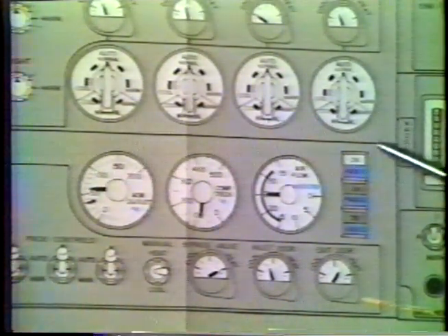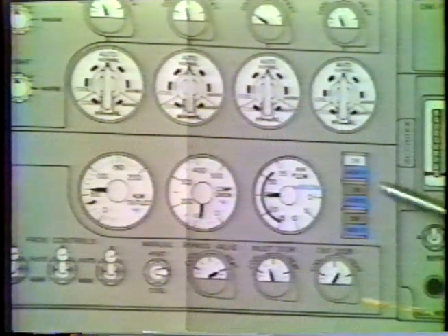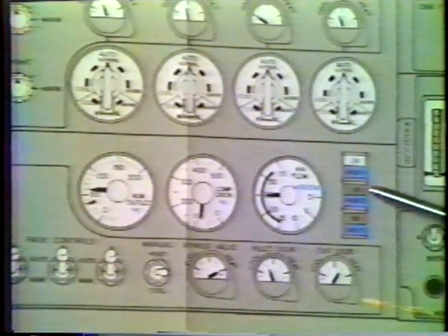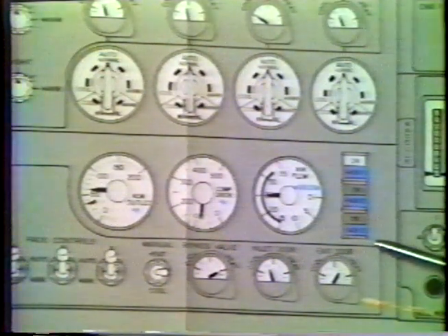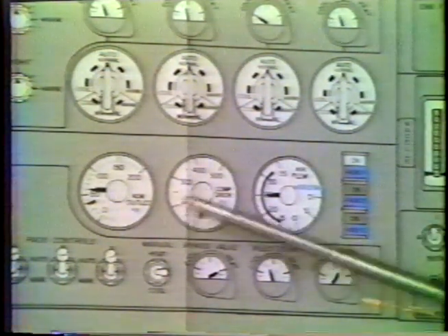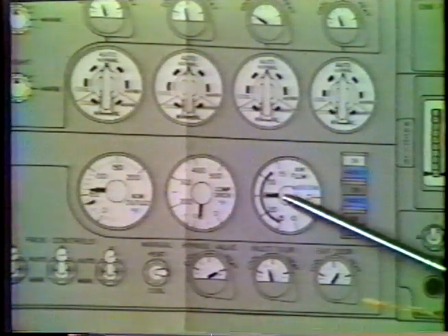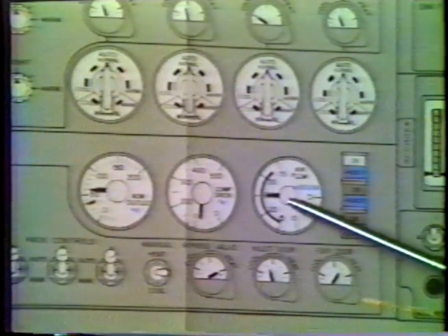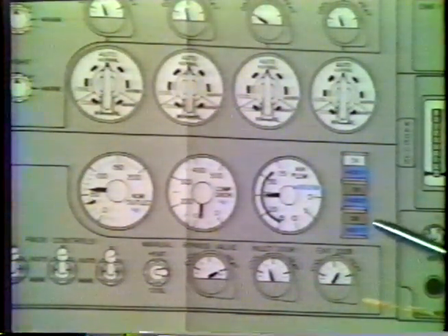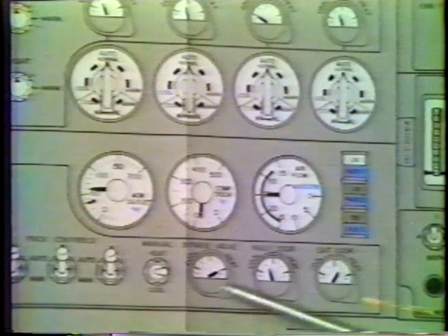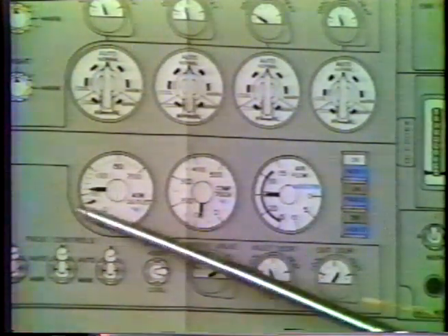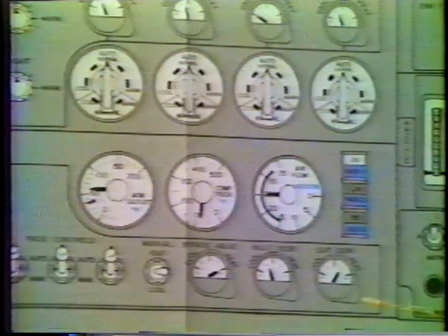If you push the push buttons to the point that none of them are in, none of the lights are on, all of them are looking at PAC number 1 except the airflow. The airflow will not register at all. So if nothing is selected here, then the bypass, inlet, and exit door and the temperatures will look at PAC number 1.